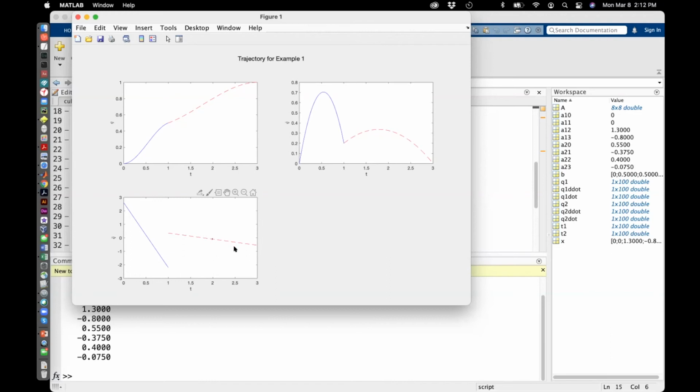You get the same thing with the second profile. The acceleration is actually discontinuous. If you want to avoid this, you want to put in more conditions, which will make that equation fifth order. Now there's another problem with this kind of profile: the velocity starts at 0, but then it blows up to 0.7 before it goes down to 0.2.